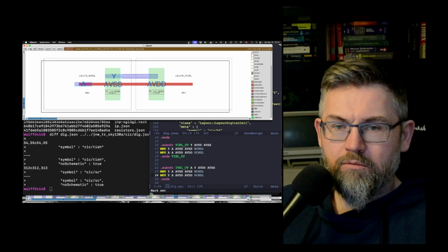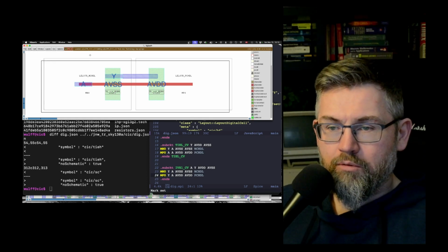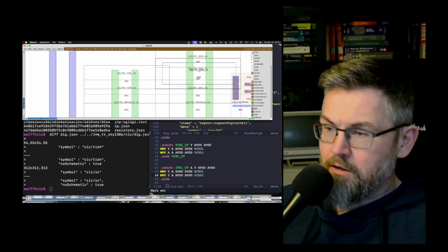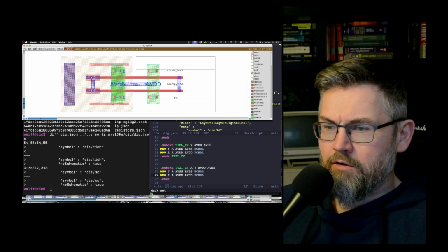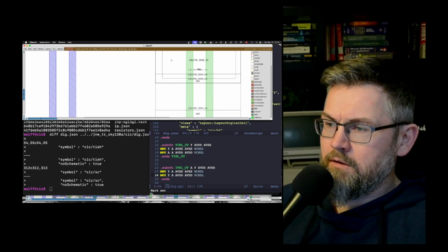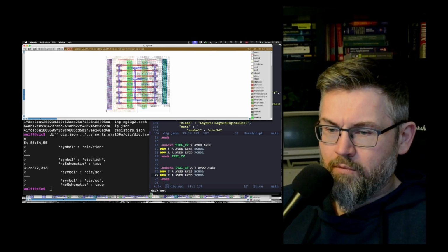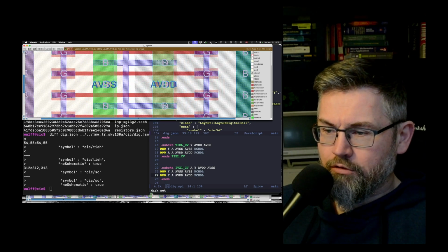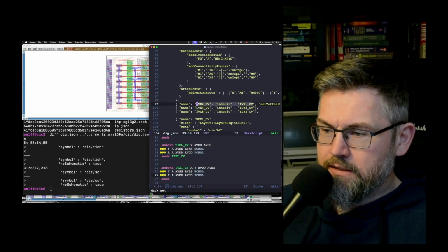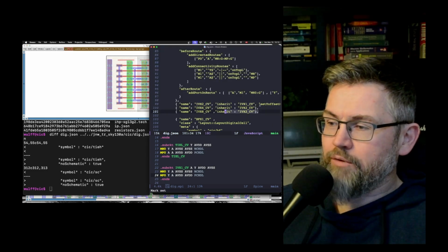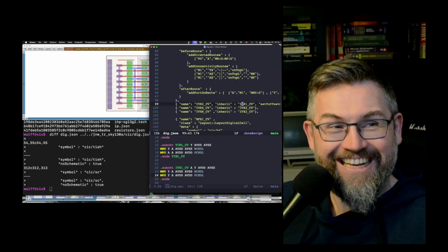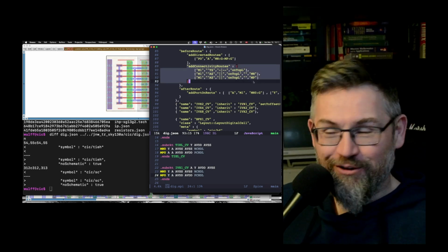So if I, I don't remember the command for go up. Oh, cool. Up hierarchy. So let's select the 2x cell. No, that's too boring. Let's select the, is there an 8x? Okay, perfect. So this is sort of the 8x inverter. And what you can notice is that it still just inherits the 2x. And the 2x inherits the 1x. So that inherits this description of the route.